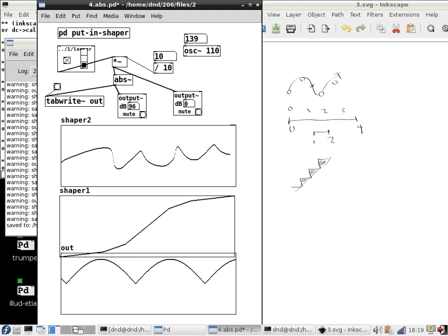One tiny thing about the absolute value as a clipping function is that it's always non-negative, and so there will always be a DC component, and so you will have to high-pass filter it before you do anything else with it. But then once you've done that, you've got yourself a nice thing that can be loud or soft, and it's always clipping. It's not even just approximately true, it's exactly true that if you scale the input, the output scales. But it's not linear, because if you added two things in, you would not get the sum of the two things out.